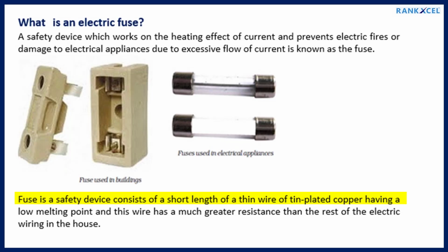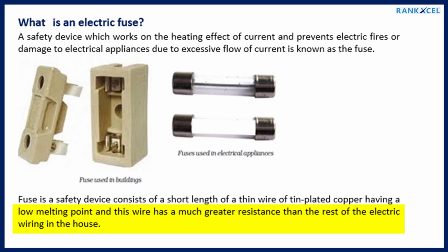A fuse is a safety device consisting of a short length of thin wire of tin-plated copper having a low melting point, and this wire has a much greater resistance than the rest of the electric wiring in the house.